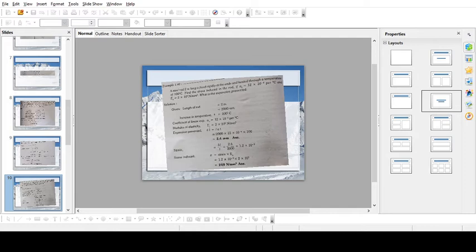Sometimes a brass bar or brass casing and a steel bar, or a brass tube and a steel rod. So like that, it comprises two kinds of material or more. Right? So if you are considering a unit length of compound bar, a compound bar is nothing but a bar which is made up of two or more kinds of materials, and let elongation be delta L under the rise of temperature.